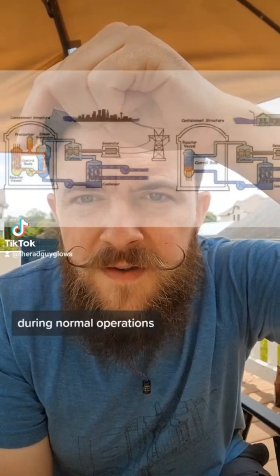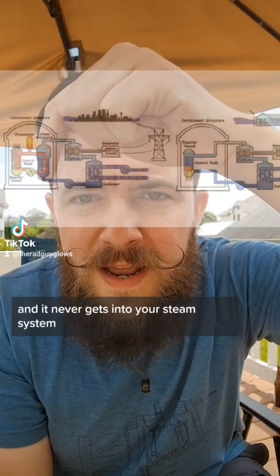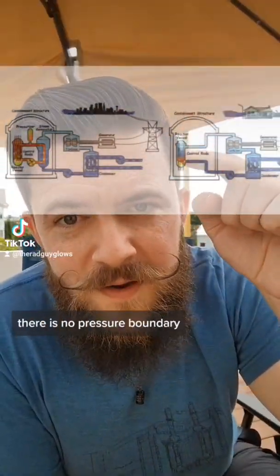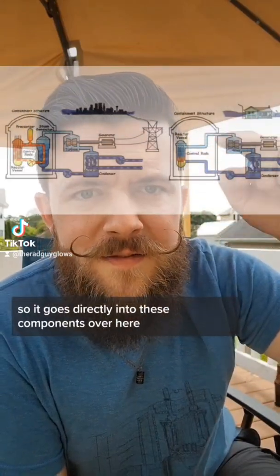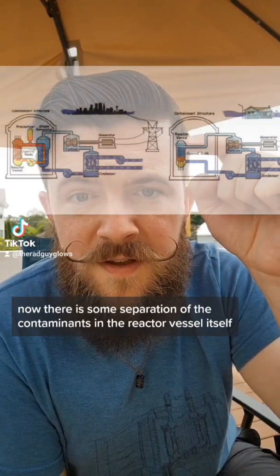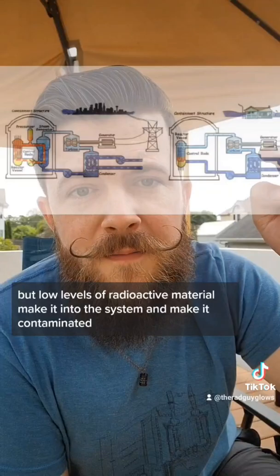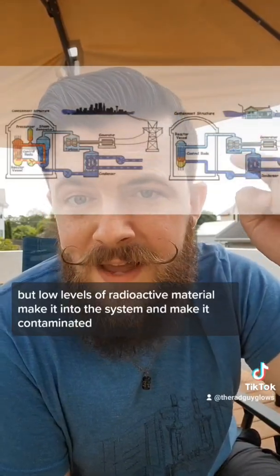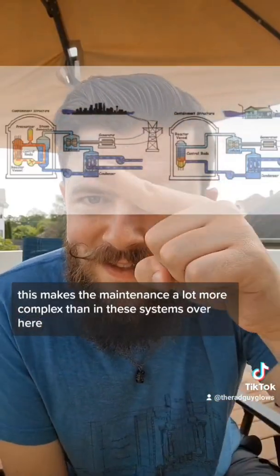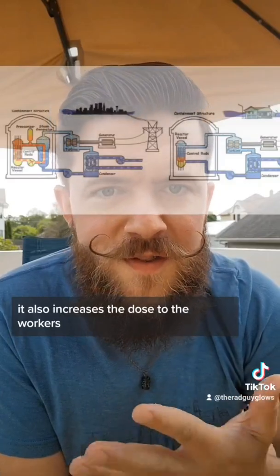During normal operations, there is slightly contaminated water that flows through this loop and it never gets into your steam system. Now in the boiling water reactor, there is no pressure boundary, so it goes directly into these components over here. Now there is some separation of the contaminants in the reactor vessel itself, but low levels of radioactive material make it into the system and make it contaminated. This makes the maintenance a lot more complex than these systems over here. It also increases the dose to the workers.